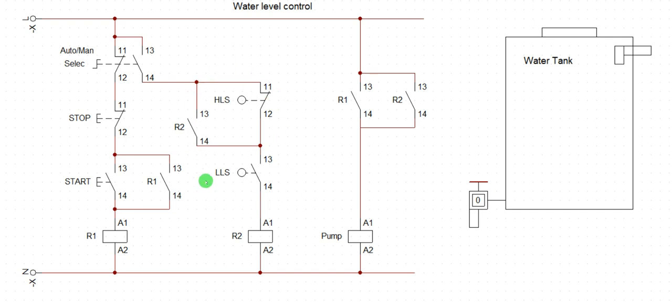Once you activate this, here is going to open and here will close. So the automatic mode will be activated. And the operation is going to be subject to the position of the switch. When you activate this, the operation will not take place unless any of this switch is in open mode and you need to close it for the operation to commence. So let's do that now. Let's first of all activate our manual. I put on the logic here. The pump is pumping water here. It will pump to infinity unless you come here and shut it down. Okay, when it gets filled up, you come and shut it.